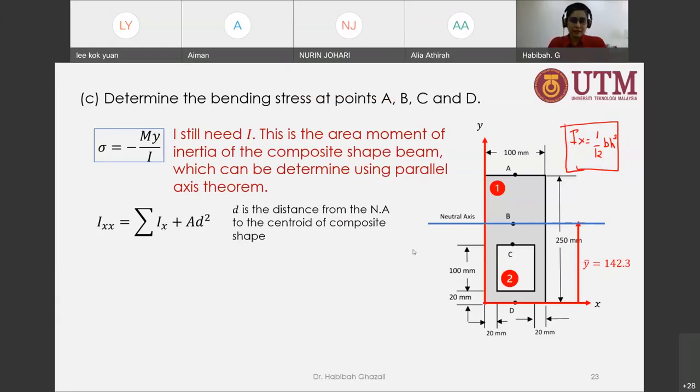All right, so here the parallel axis theorem has two terms that you need to add up. You need to do it for each of the regular shapes, and if it's being drilled out, it should be negative, and the one that stays is positive. So I have Ix for shape 1, and now I have this term here, D. What is D?